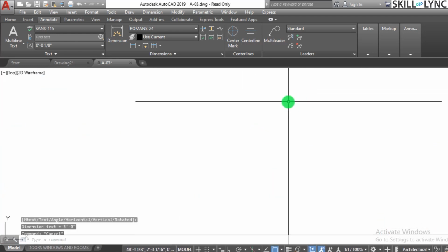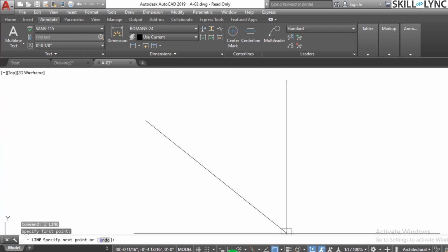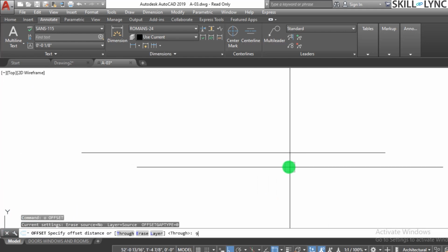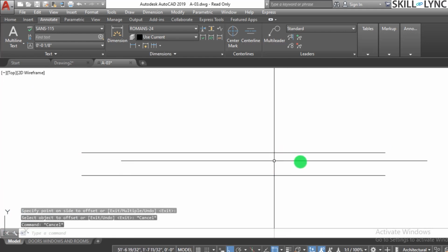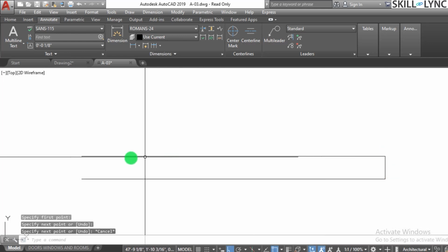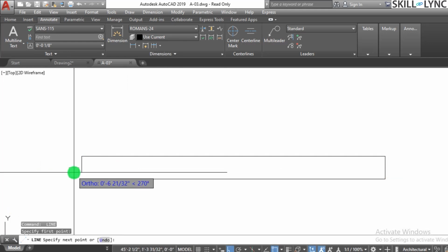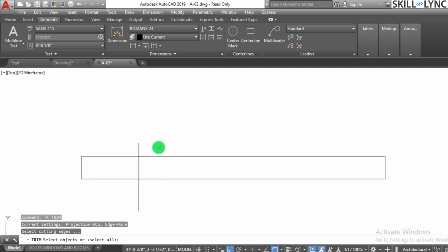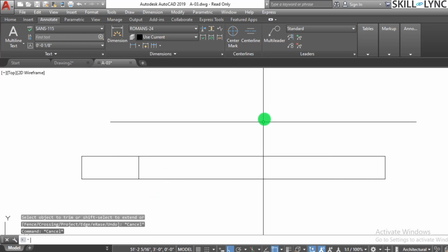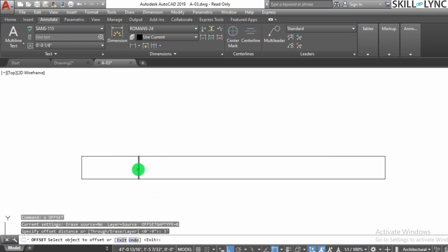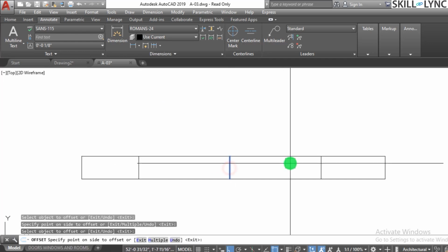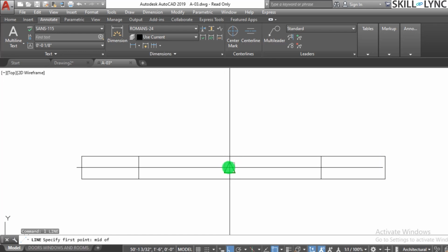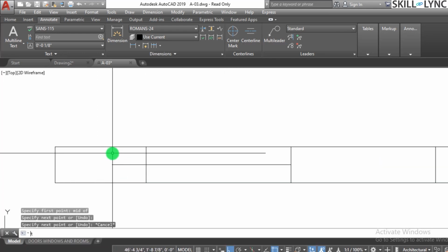For example, I just sketch a wall over here. Let's say this is a 10 feet wall that I want to sketch with 9 inches thickness here, and I'm using feet inches in this because the drawing is calibrated in feet inches. Let's say I have got some multiple windows over here. Now I just wanted to mention the standard dimensioning techniques that we use. So let me put the windows over here, and then we will dimension this. Here I'm giving a symbol of the window over here, and then we will be doing some dimensioning here.